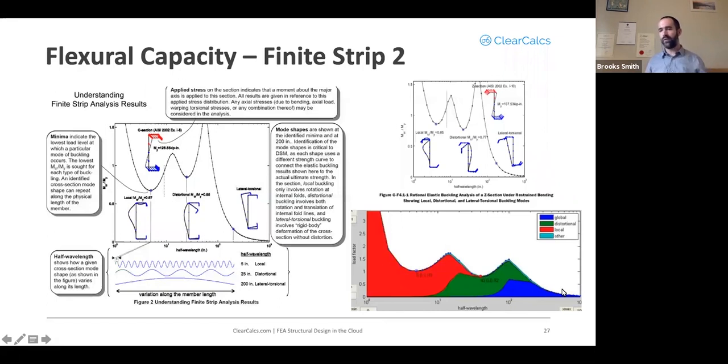If you are using the finite strip method for calculating your global buckling capacity, then it depends upon length. Because again, your length relevant for that will just be the full unbraced length of your beam. And that's going to vary depending upon the exact support structure for your beam. However, M0L and M0D are going to be generally the same for a given cross section, no matter what.